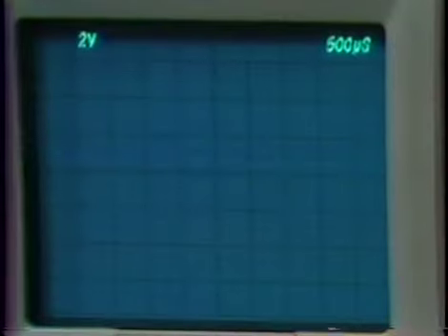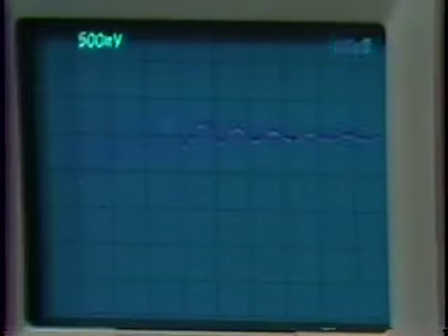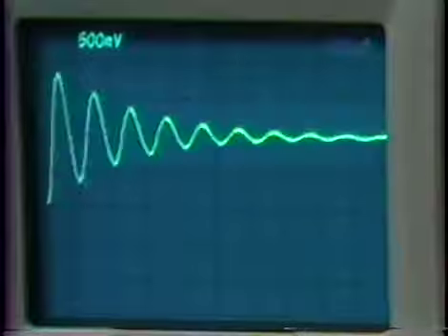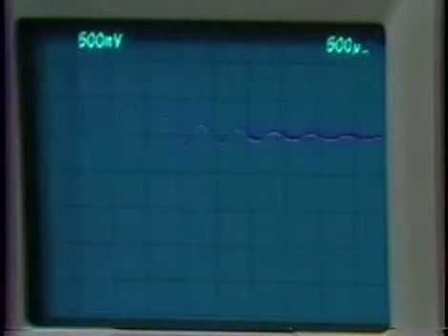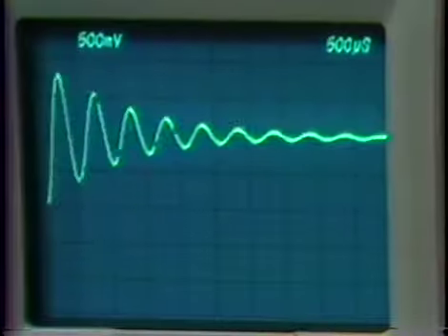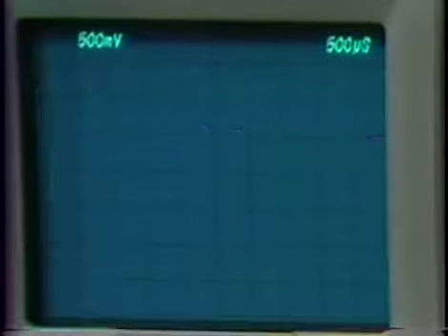And what we notice is that we now have, again, a poorly damped step response. We only have about 15 degrees of phase margin, as I indicated earlier, for A0 equals 80. But we're now certainly crossing over at a high frequency, above the 950 hertz critical frequency, above the higher value in the S-plane where the roots come back.